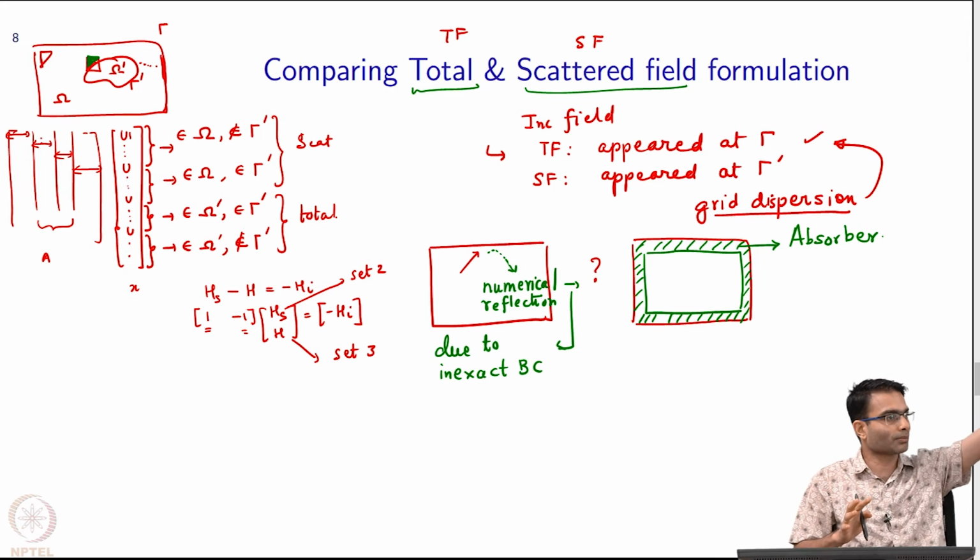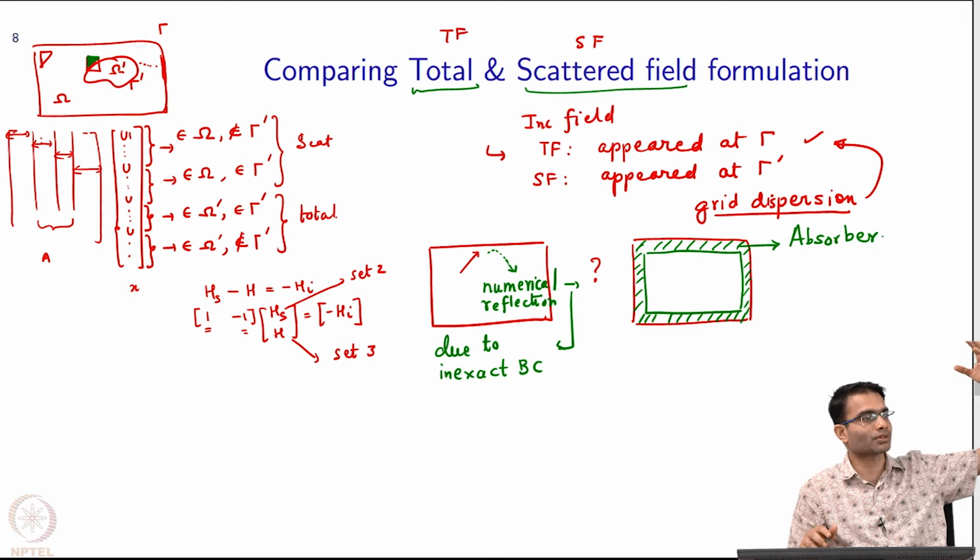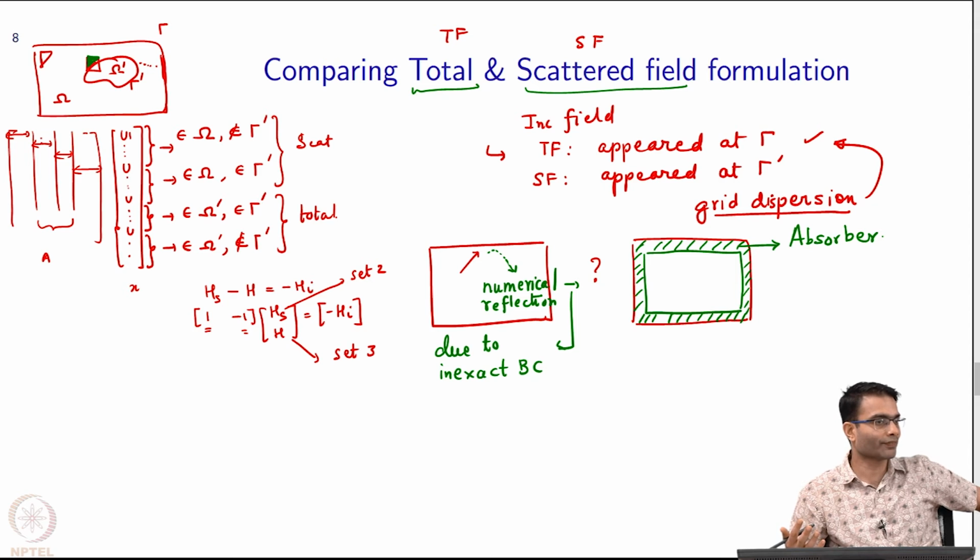Physical problem, I put some layer over here which absorbs. Absorbs means the first word that should hit your mind from your undergrad EM course is skin depth. What is skin depth? If you have some conductor, wave goes inside, gets absorbed and dies after skin depth. But what made that property to have different levels of skin depth? The loss in the medium, right? Conductivity basically. If there was no conductivity in the medium, what would happen? Would there be any skin depth? What is the skin depth of vacuum?